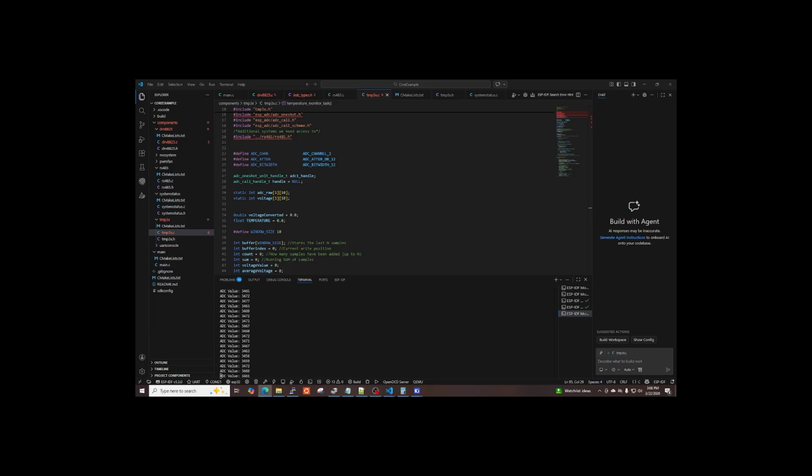Or GPIO 38, 39, and just swap with another function. Swap with like maybe a limit switch or something. And that won't be that big of a break because we'll basically be swapping 2 inputs. But like I said, we'll have to do some testing on the dev board to make sure we get it right before we commit all the changes to the next revision.